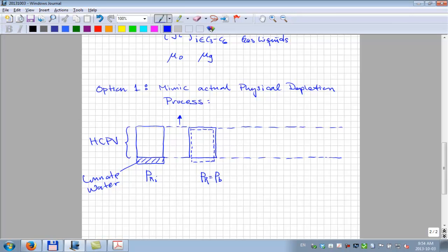The water phase has solution gas. You can't get away from it. So as the pressure drops in that water, some of that will leave because of the new equilibrium. Probably will leave because those components would prefer being elsewhere in the oil phase.